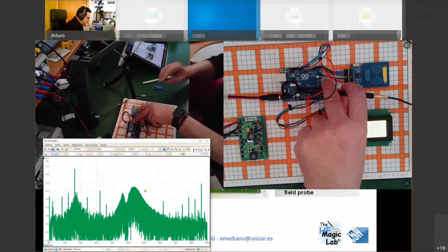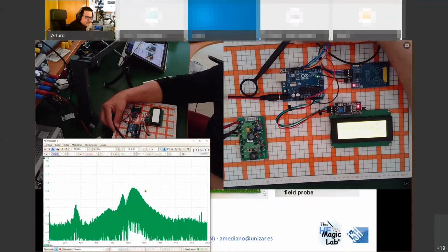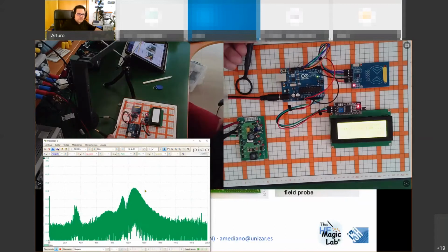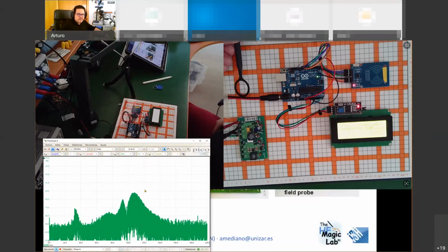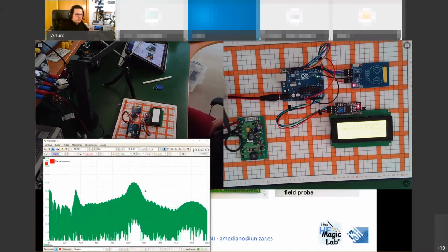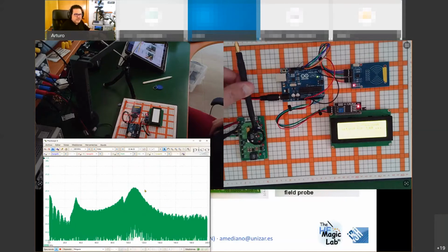Okay, so if I go to the cable, I can identify that in this cable there is a strong emission at the frequency of interest. Look at the effect of the magnetic field orientation. If you rotate the probe 90 degrees, the signal you will be picking up will be lower. It's not reduced a lot because the cable of my probe is also picking up the signal. When I go on top of the converter, I can identify that the signal is really big.